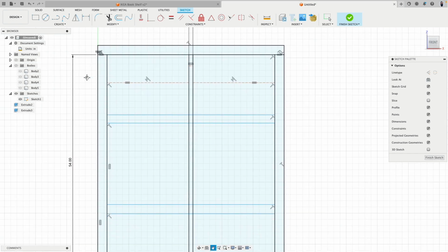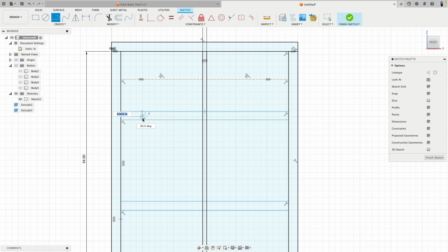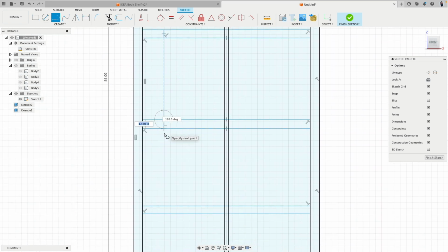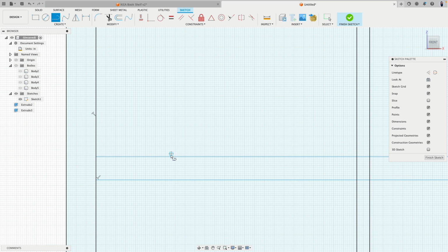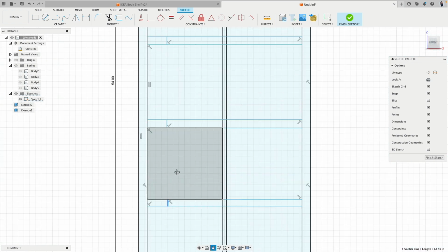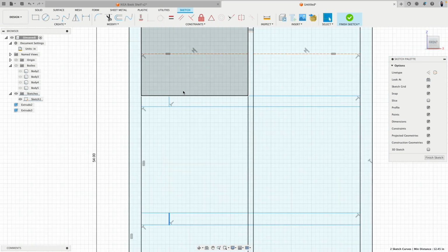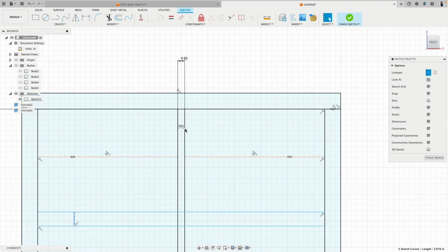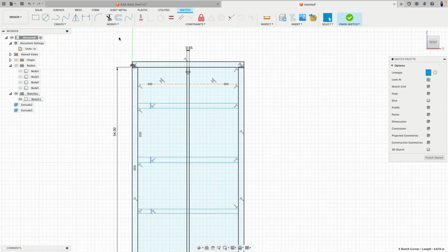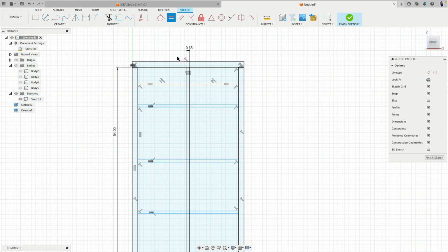Okay, I guess you start realizing what I'm going to do now. Line number 1 and number 2 and number 3. I'm prematurely stopping this line. You see there's a dot. I can select this dot and drag this down onto the line, and then this dot is gone. That means actually that these lines are perfectly glued onto the other lines. Click construction, and now here comes the trick. And say equal, flop.